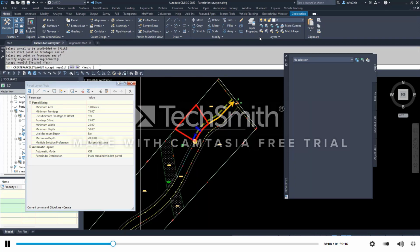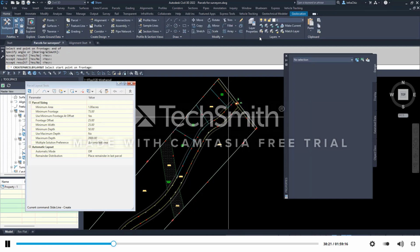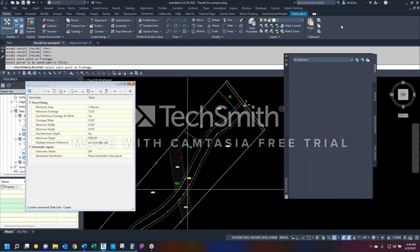Get a nice little preview. Enter. Still not bad. Enter. Looking good. Wait a second. The distance selected is less than the minimum frontage of 75 feet. What should I do? Hit OK. And it says, I don't know, even though I told it to place the remainder in the last parcel, which it did. Great. Okay. I'm going to get out of this. I'm going to just hit enter one more time, and I'm going to select my next parcel, which is down to the south. It stays in it. I'm going to go back to my easement.